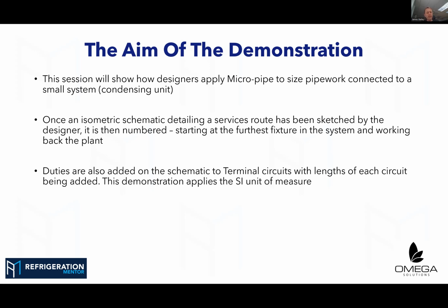This time I'm going to use an HFC/HFO blend, R448A, which, if we are still using HFC refrigerant, I hope everybody is using 448 or 449 as opposed to 404A, just due to the obvious GWP and actually lack of efficiency as well compared to newer synthetic refrigerants.